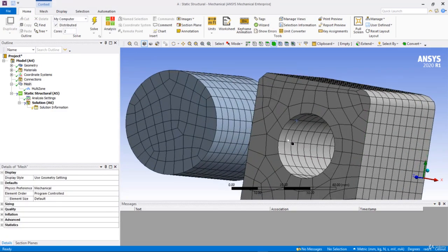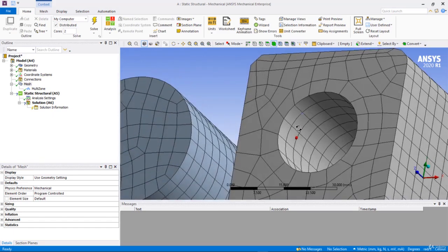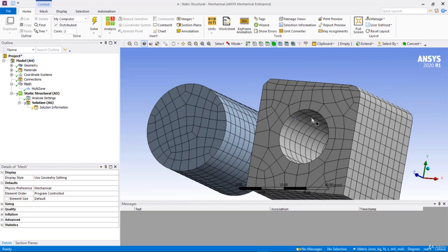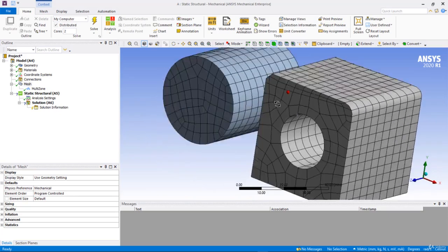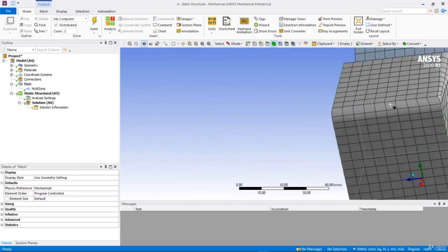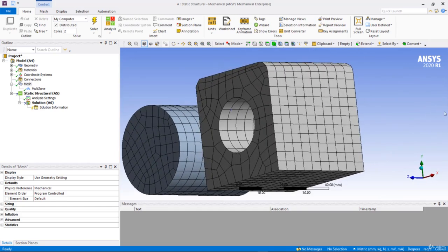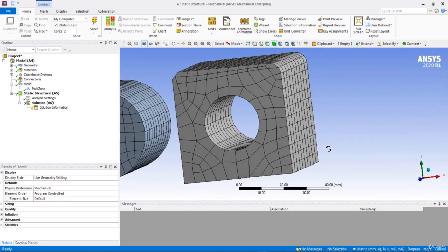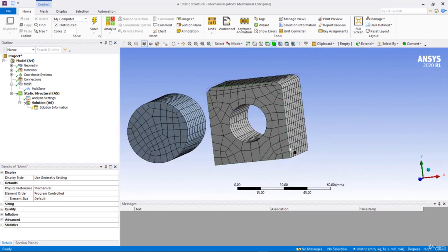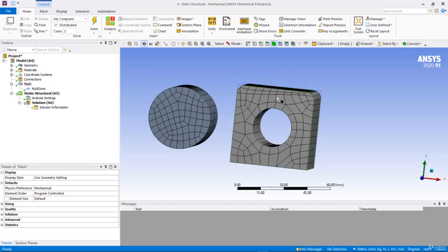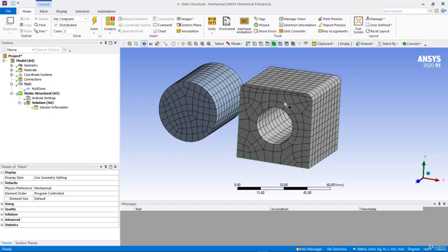So if you are able to see, using the multi-zone meshing, there is a possibility of creating good hexahedrals. What happened is, it has created a good hexahedral structure here. Outside it was able to create hexahedral elements, so it has created them. But sometimes, in order to fill some gaps, it will be filling up with tetrahedrons. It will be using both types of elements. And remember, for sweep mesh, this is not a simple object. For multi-zone meshing, it is somewhat a simple object.